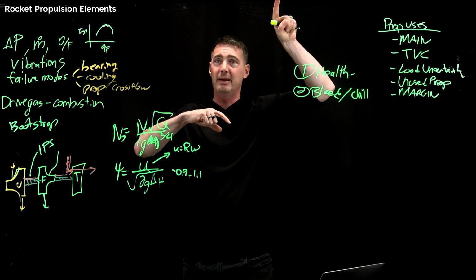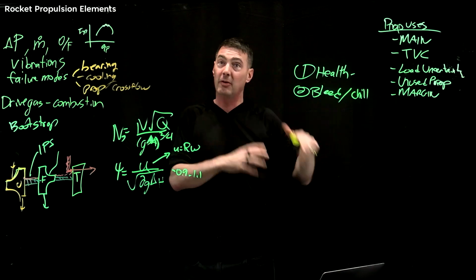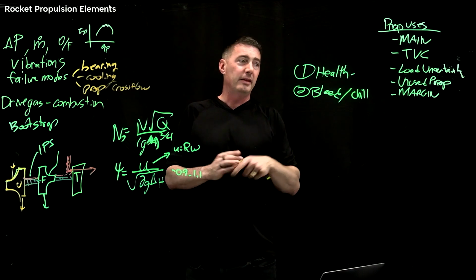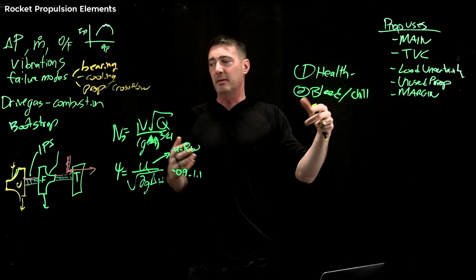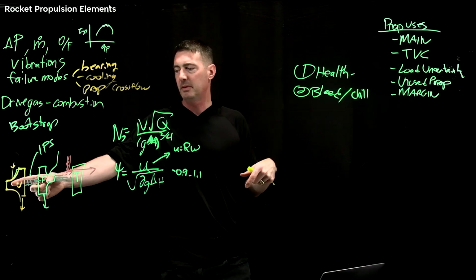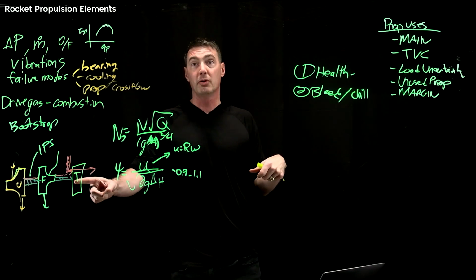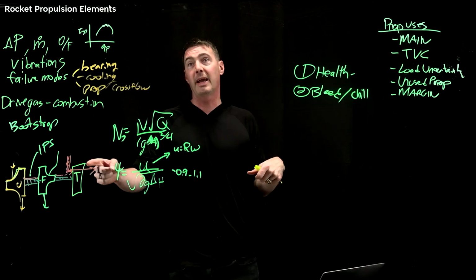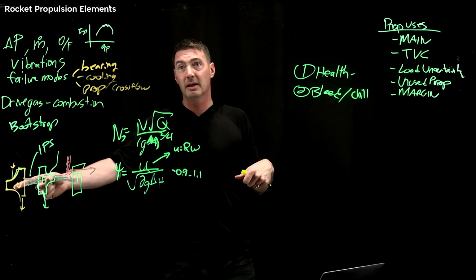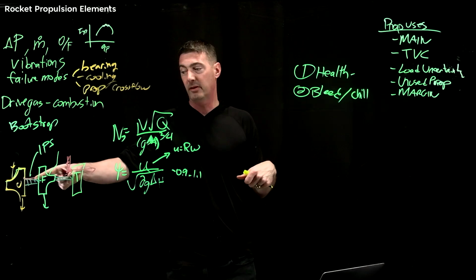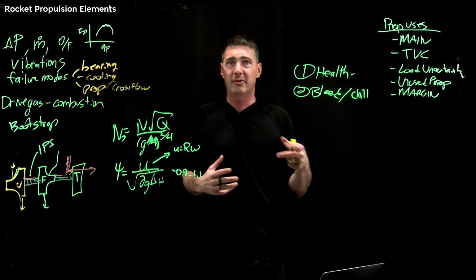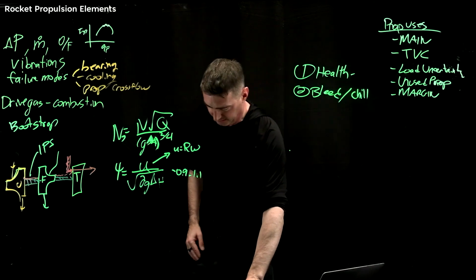So you have to have a way to get that gaseous vapor out. Sometimes it can go through the same bleed line, but it's called chilling it in. And then if you have a chill, a lot of times, again, usually back to turbopumps, your engine might be chilled or the pumps might be chilled, but you might have a go, no-go temperature on, say, the turbine. The turbine can't get down to this certain temperature. So it might be crazy cold here in aux, and it's all pretty close together. So you have some of these things that can be go, no-goes.